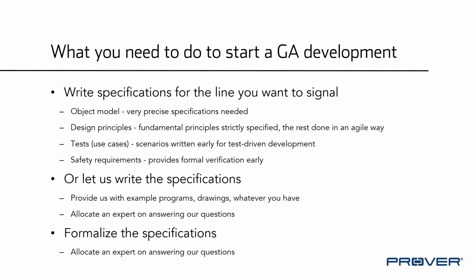So in an object model, you write down all the objects you need to support. Like there are switches, there are track circuits, there are maybe train routes, there are shunting routes, different types of objects like this. And then you write down what inputs and outputs these objects have, and also some important intermediate variables that you might have safety requirements on, such as route locking, which is not really an input or an output, but something important that your infrastructure manager wants you to prove properties about.